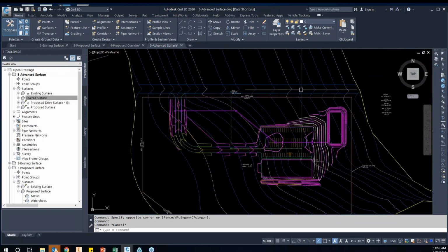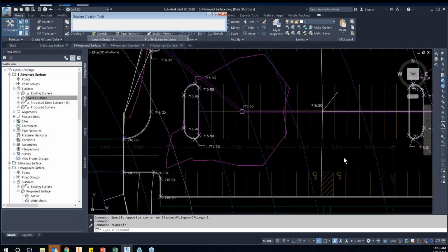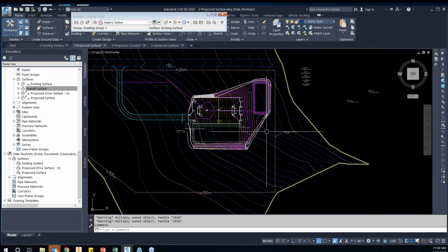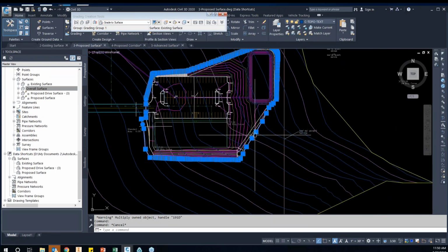Okay, if you had polylines sort of jutting out like we had before, you can add yourself a boundary on the outside of this surface. What you would want is just a boundary to represent the outside of that surface, something that surrounds the surface, sort of like this guy.